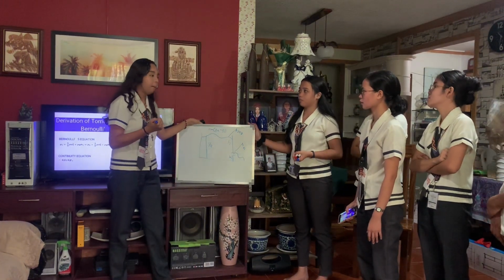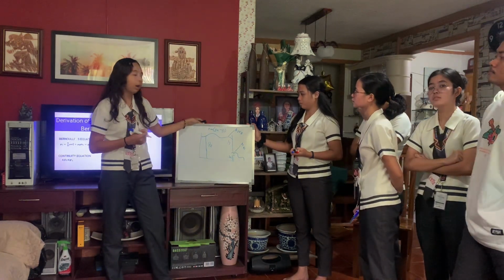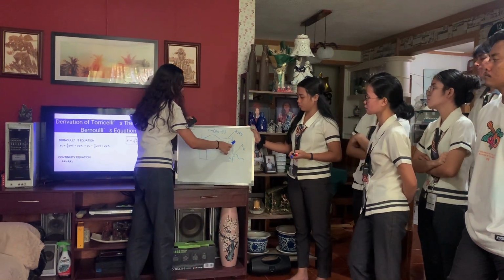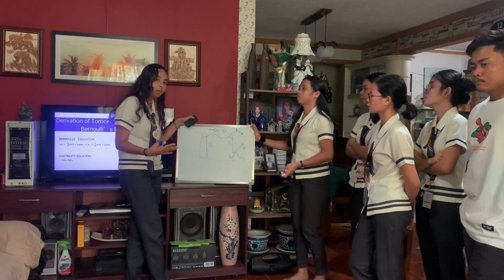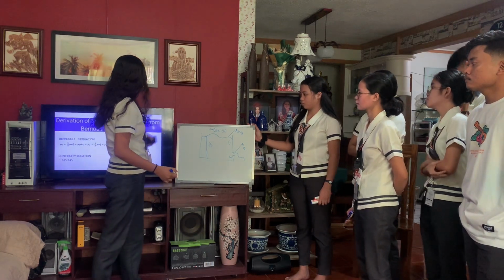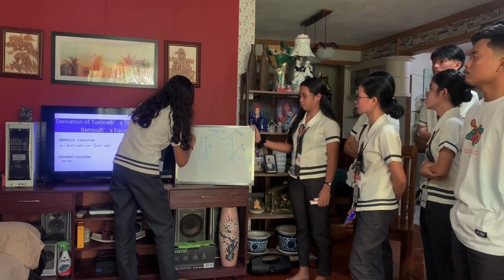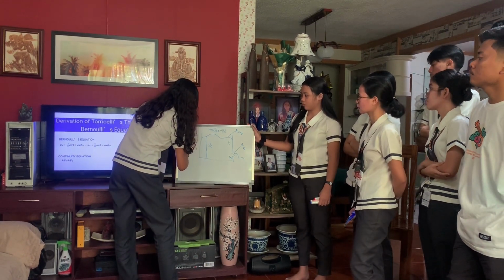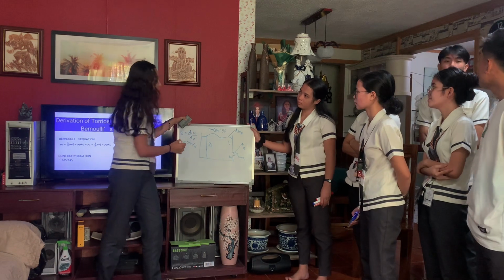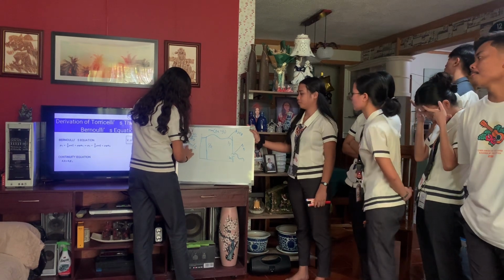Now, let's make an assumption that relates to the velocity of the water flow. You can see here that we have a continuity equation. If we assume that this cross-sectional area A2 is much larger than this cross-sectional area A1, the continuity equation gives V2 equals A1 times V1 divided by A2. This becomes 0 because area 2 is a large number, and a number divided by a large number is closer to 0. So we assume that V2 equals 0.